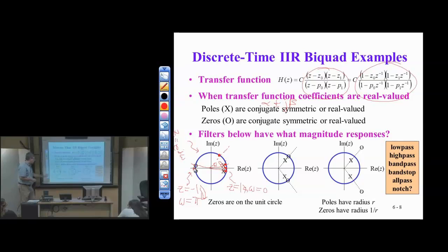So that's now. What if I switch the order? What if I put the poles over close to pi, where z equals -1, but not on the unit circle? And I put the zeros over here close to z equals 1 and on the unit circle. What would that filter be in selectivity? It would be high pass. Okay. Let's think about another one while we're at it. All right, so let's go. I'll draw that last one. So again, I take a.